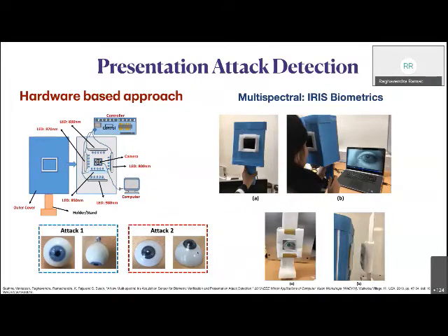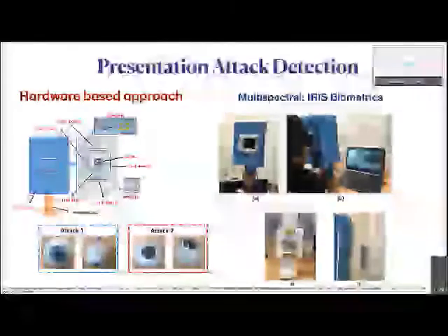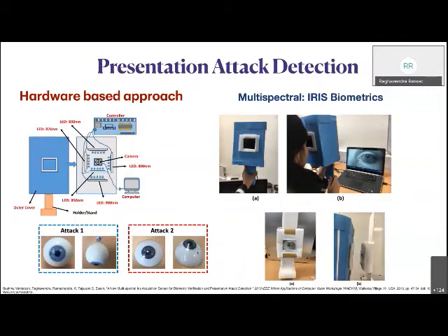But with near infrared, just with near infrared, they have recently shown that the iris recognition system can also be deceived or attacked with new kinds of artifacts. If I present an iris with a print attack in a near infrared system, it is quite easy to detect those kinds of attacks with simple software. But if you have very sophisticated attacks, like display attacks using a special kind of display like a Kindle display, obviously it is not easy to detect those attacks. That is the motivation why we need to design these kinds of sensors.